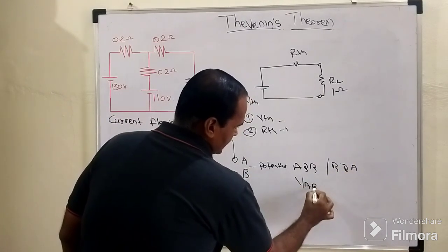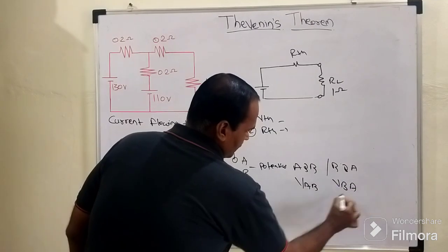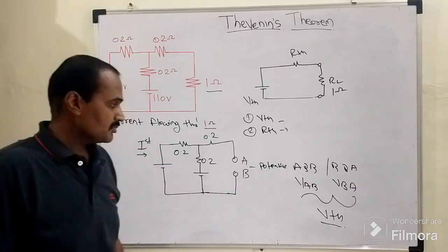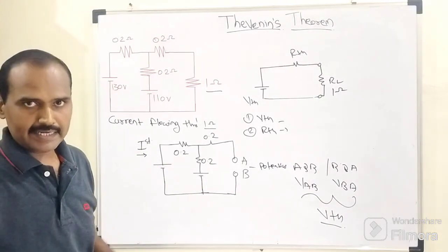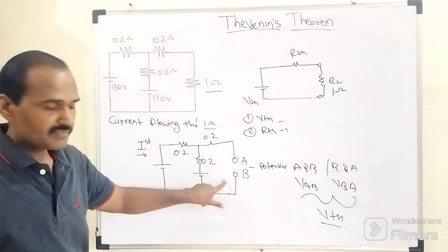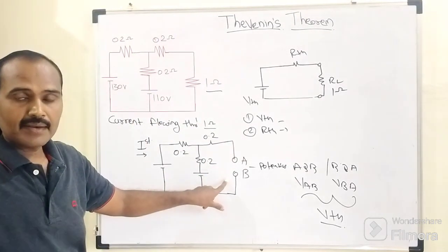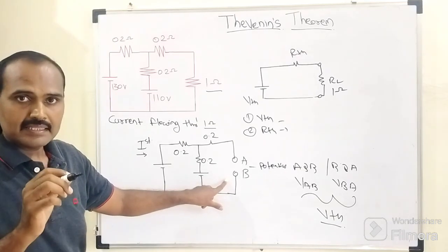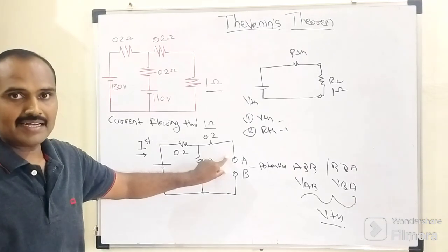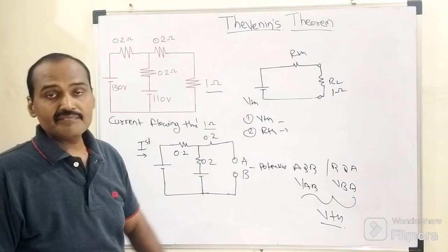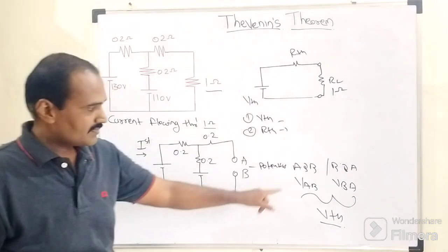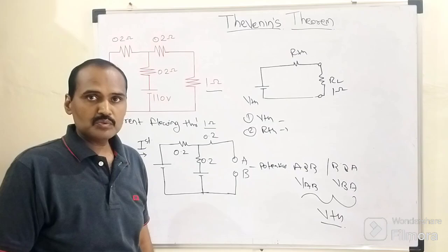That voltage can be called VAB or VBA. That is nothing but the Thevenin voltage. This is the most important step of this Thevenin circuit example that we need to understand. Once that target resistance is replaced with these two open circuit terminals, we need to determine the desired potential lying between these two terminals, and that potential can be considered as the Thevenin voltage.